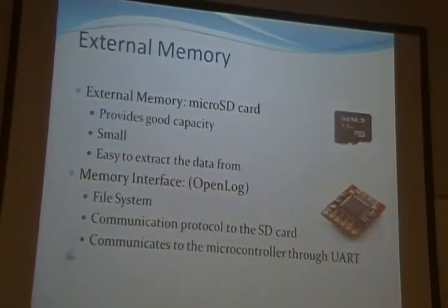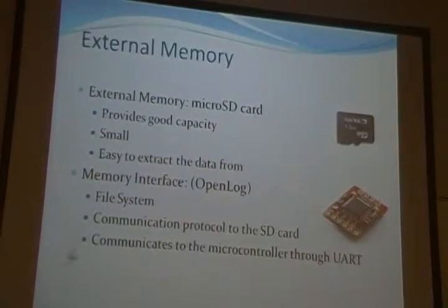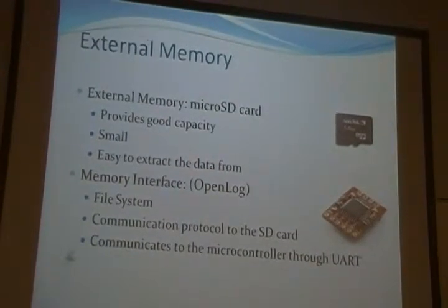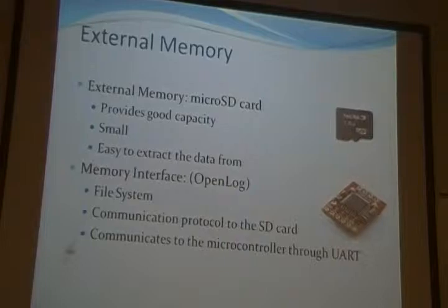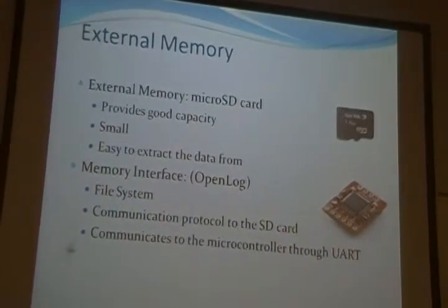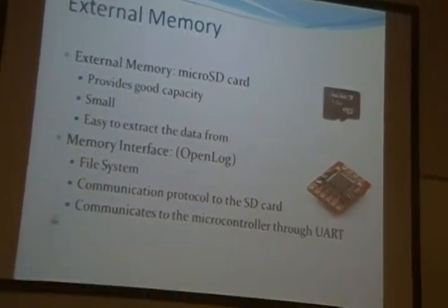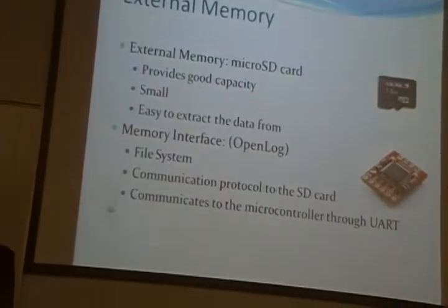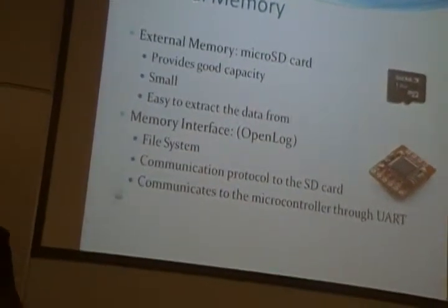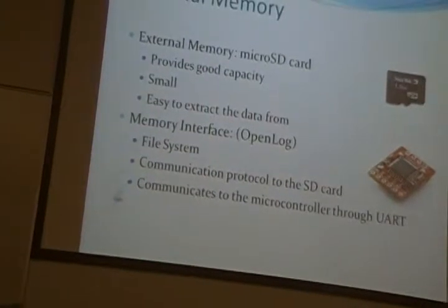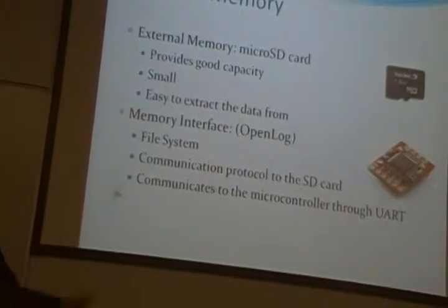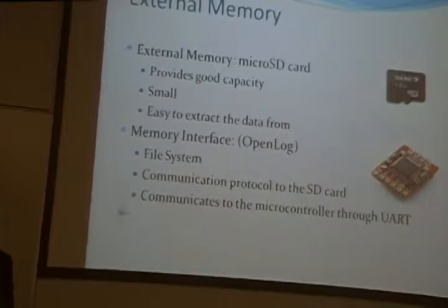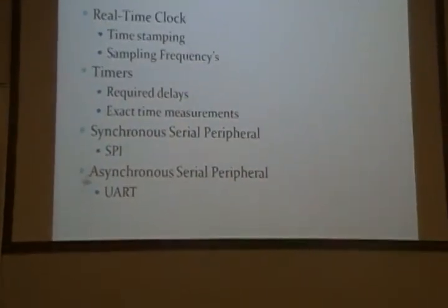For our memory interface, we used OpenLog, which implements the file system and communication protocols necessary to communicate to a micro SD card, and this reduces the load on our microcontroller so it can do the most important stuff. And it communicates to the microcontroller using asynchronous UART.